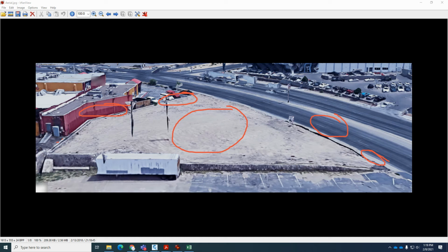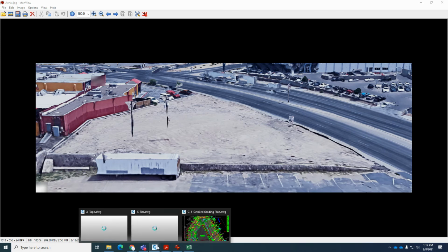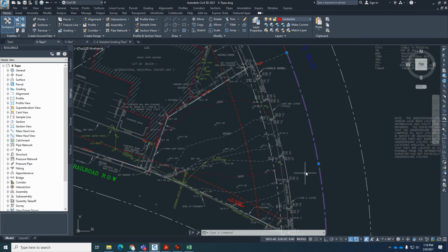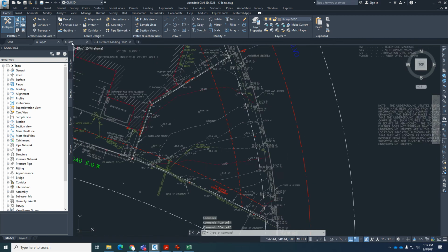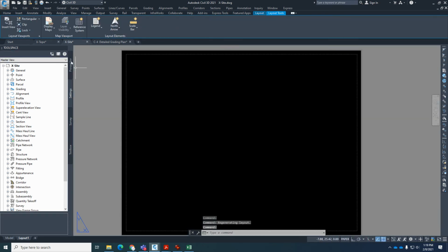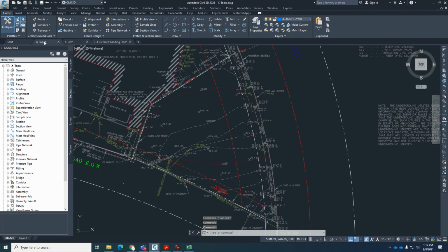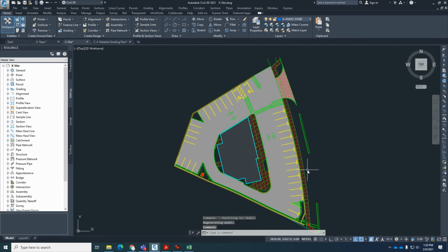Okay. So before we do anything, the surveyor has to go out there first and collect the data of what's there before the project begins, and before we start design. That's the file we'll be getting. After that, the architect should, and here's a key word, should, on the site plan, use the topo and the property lines to develop their architectural site plan.